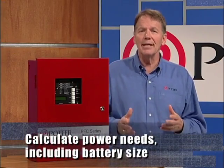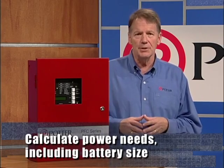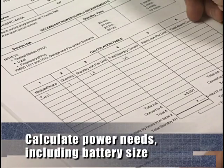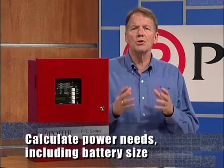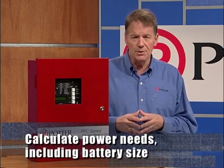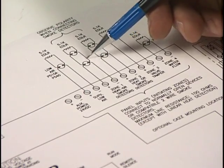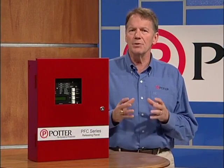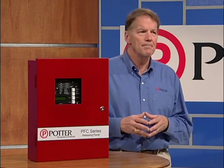Next, calculate how much power is needed based on the devices that will be included in the system to determine if the power supply and wiring are sufficient. Remember to include your battery calculations to determine the proper battery size for the system as well. You'll want to prepare a detailed drawing of the complete system, including wiring hookup. Place a copy of this drawing in the panel cabinet for future reference.